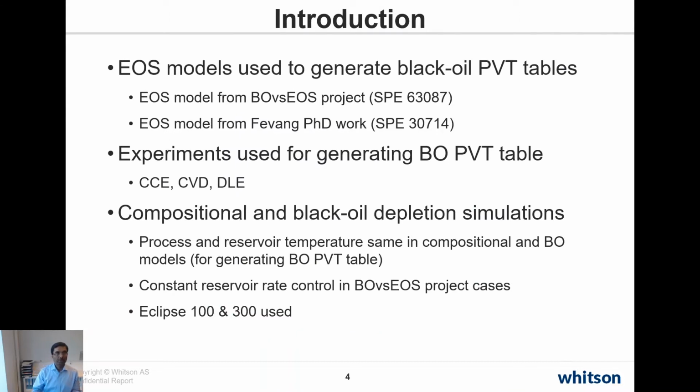What we have done is taken an equation of state model to generate black oil PVT tables, and these EOS models are taken from SPE 63087 and SPE 30714. Then, using the equation of state model, we generated black oil PVT tables using CCE, CVD, and DLE experiments.